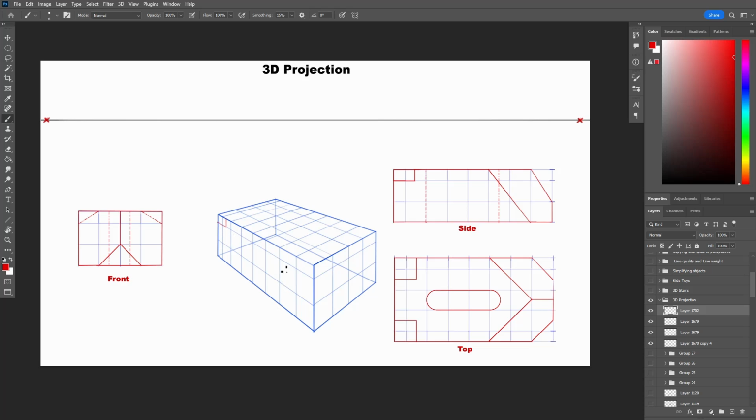Next, we move on to the slope. The first slope hit the 1 unit corner in the bottom, but the back slope seems to be behind. If we shift the top view, we can see the slope we are looking at is in the center of the object from the front. And if we shift the front view, it seems like it's sitting on a triangle. So you have to check all 3 views at the same time, before adding any lines there. So from the top view, this line will go toward the front view at a 1 unit mark. From there, it will go the same way to the other side.